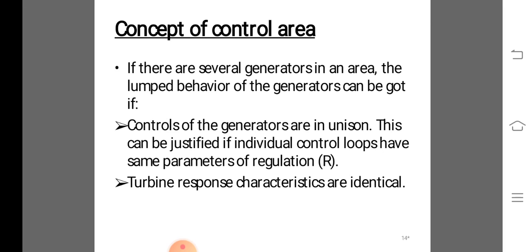This will be achieved using the supplementary loop, which uses the integral controller to change the reference power setting so as to change the speed set point. The integral controller gain, represented by K1, needs to be adjusted for satisfactory response in terms of overshoot and settling time of the system.